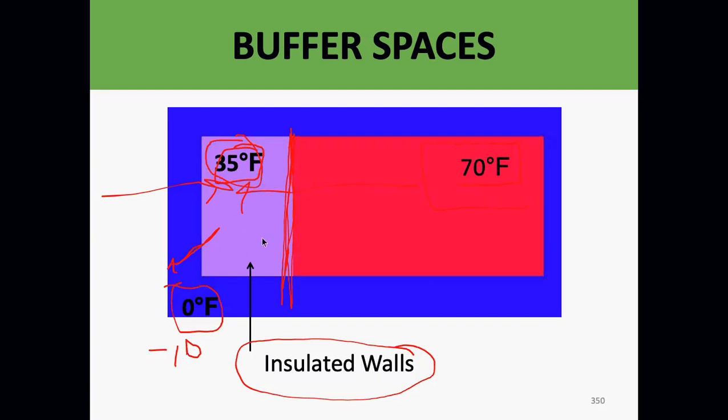Okay, because the water inside the furnace will freeze. I wouldn't put a boiler out here either for that exact same reason. Of course, if I had a boiler out here, the heat would probably make it warmer, but I just wouldn't chance it. So I never install that type of furnace in an unconditioned space.